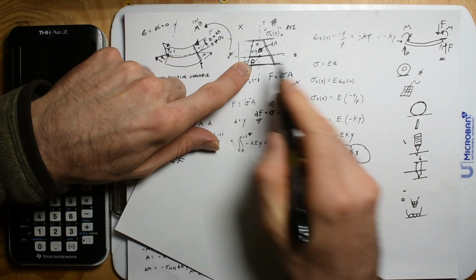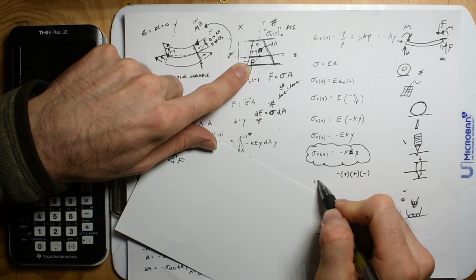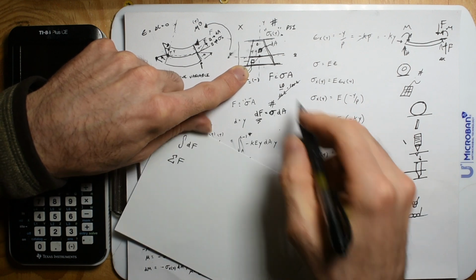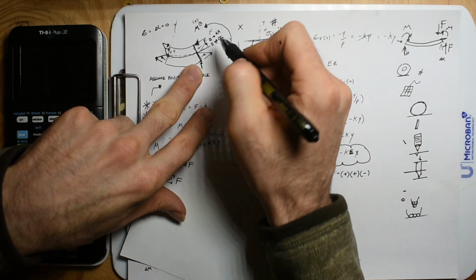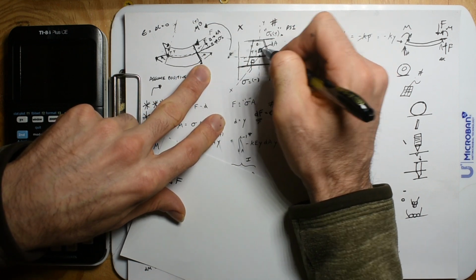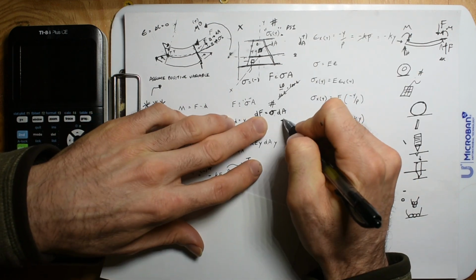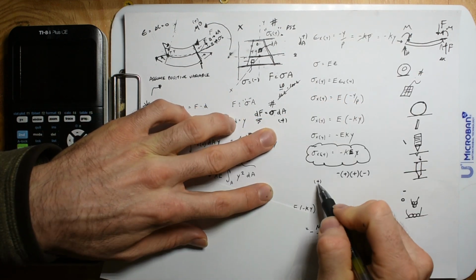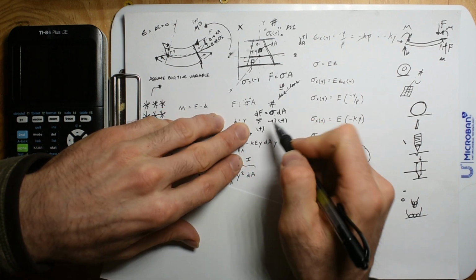Let's say our value of y is negative. Cool, that's going to give me a positive stress. And then the area, just by sign convention, if this is the x face, the dA is going to be a positive area. So I have a positive area, I have a positive PSI, and that's going to give me a positive force.